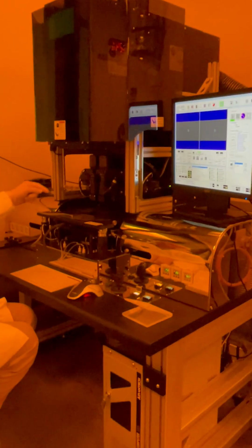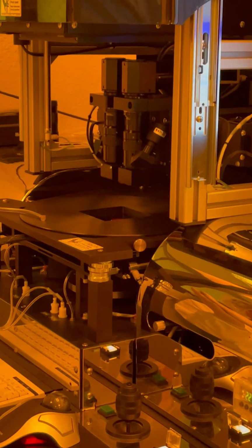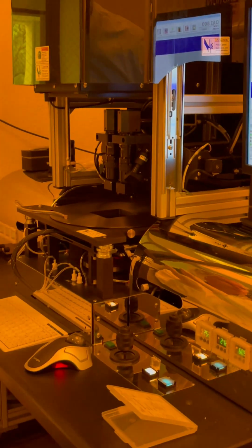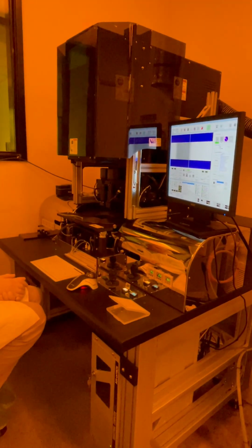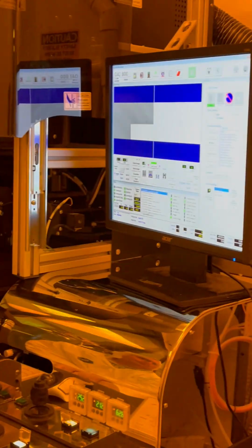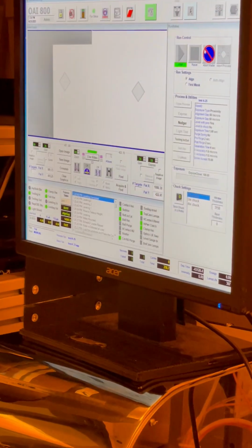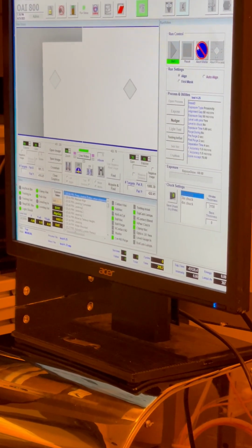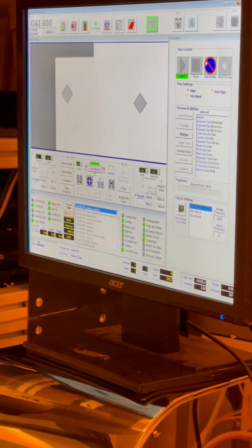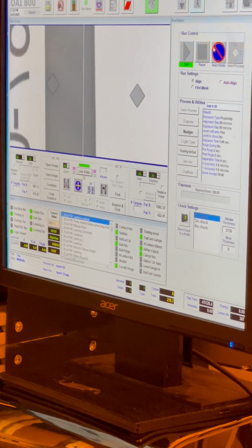So that's, I don't know if you can see that, but that's the leveling pins that come in. There are 3 stainless steel balls that are now sandwiched between the mask and the wafer, and that sets the gap. So it's done leveling, and so now it comes up and it's moving to whatever position is saved here. I don't know where it is. I might have to move it. Okay, so now it's enabled the joystick, and I think the targets are over here.